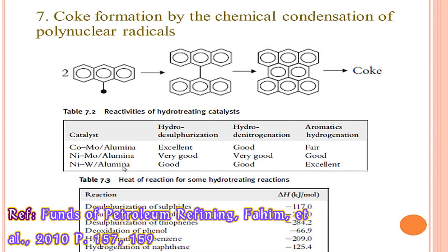Catalyst is quite sensitive to the metal deposition, which is one type of concern that we have. That's why we need a guard reactor to get rid of some metal trace before feeding all the feedstock into the reactor that contains this kind of catalyst.